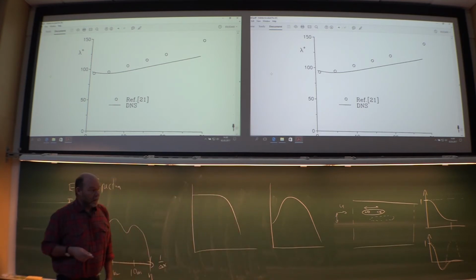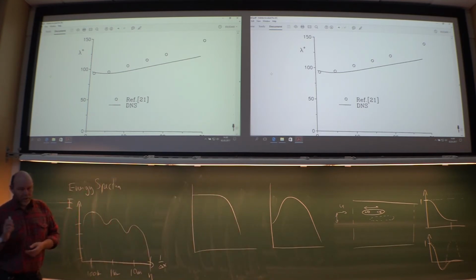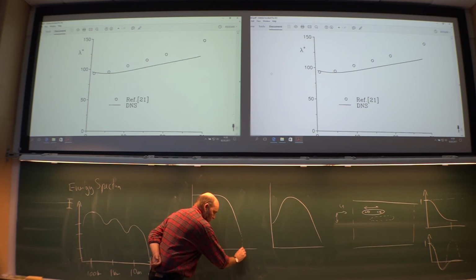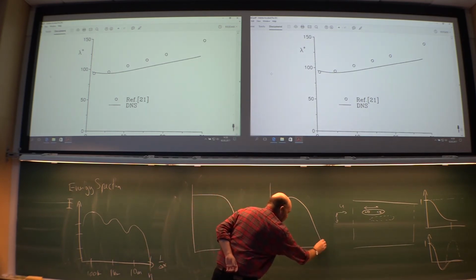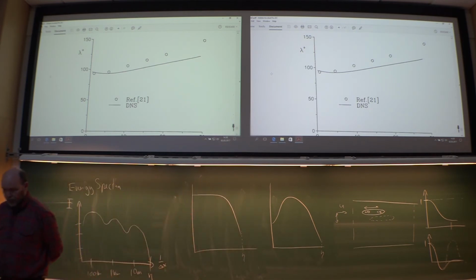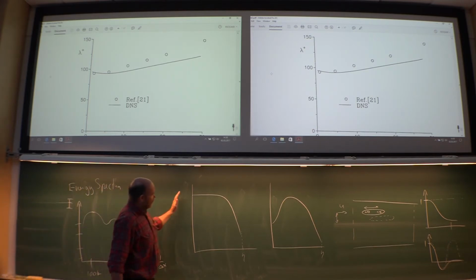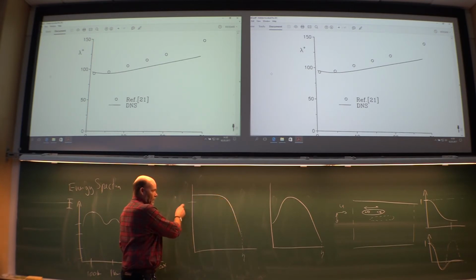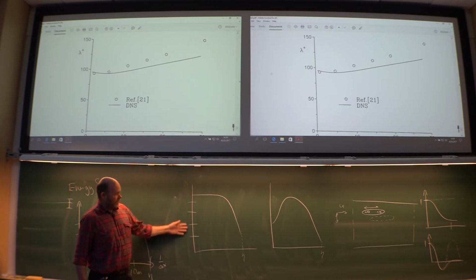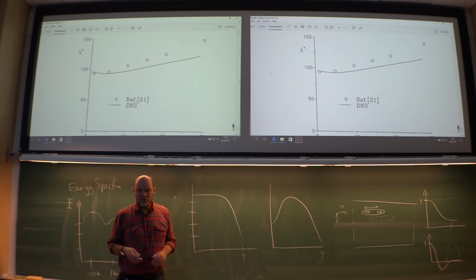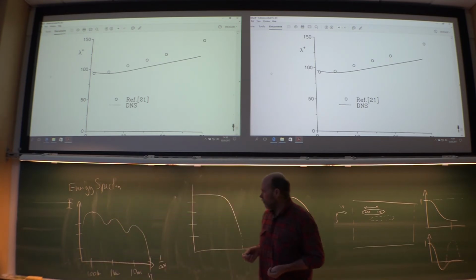These energy spectra can also be a valid aid with the DNS. When you plot them, you should get your Kolmogorov scale here. I mean, that should be your finest mesh, of course, the smallest delta X or delta Y or whatever that you have. Then you have resolved everything. So if you get an energy spectra that drops many, many decades, should be several, 6, 7 decades, then you don't have any energy left, and you have resolved absolutely the major part of the energy.